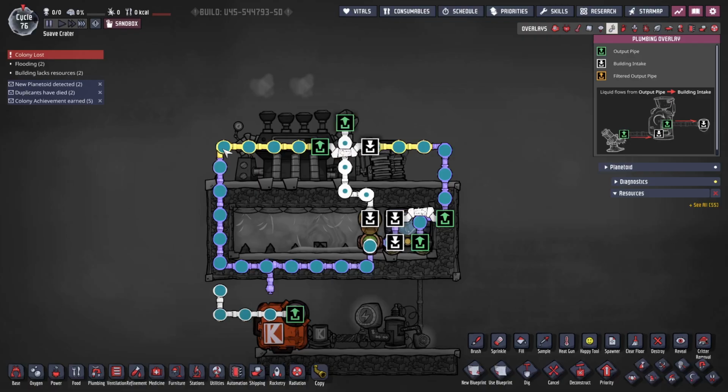We can obviously extend the radiant liquid pipe network in order to cool down a larger area, but that would also increase the temperature of the liquid inside the pipe. So we need to make sure that the aqua tuner can keep up with that temperature increase, because it can cool down only 14 degrees. As long as the temperature is not increasing by 14 degrees over the whole cycle, that will be fine, and the aqua tuner will be able to keep up.